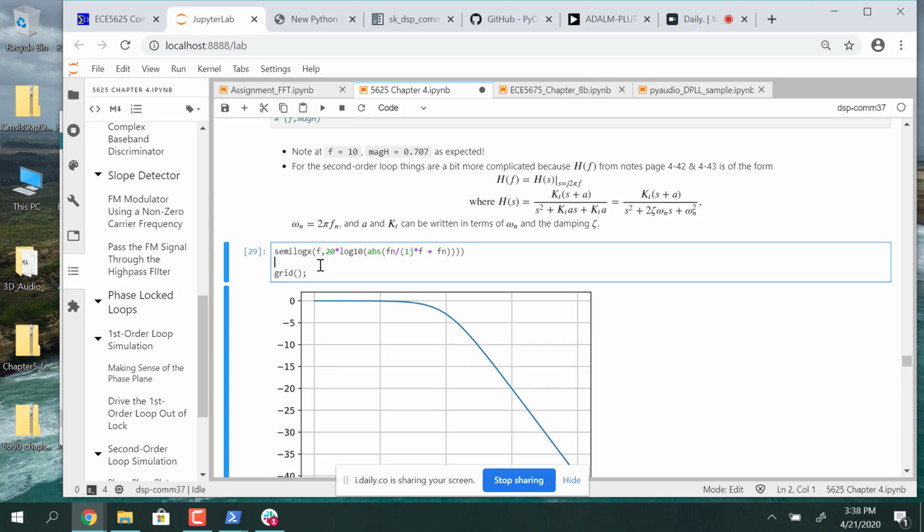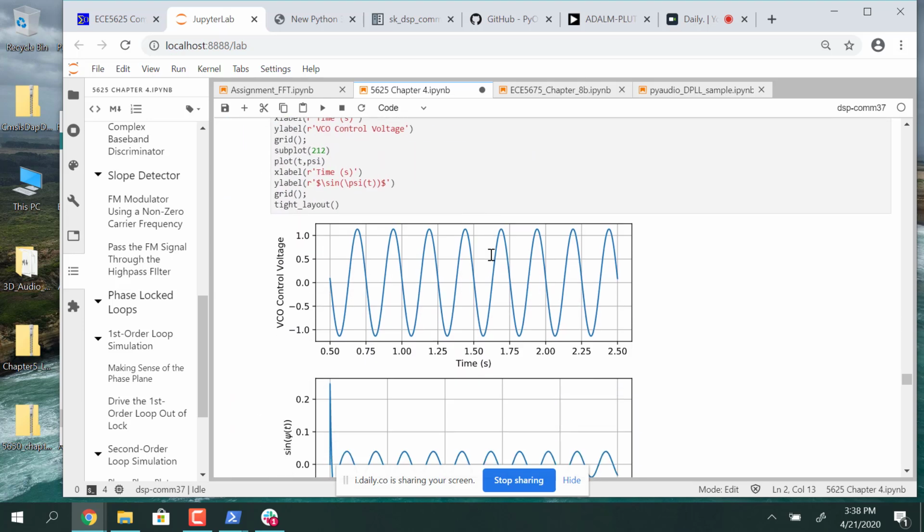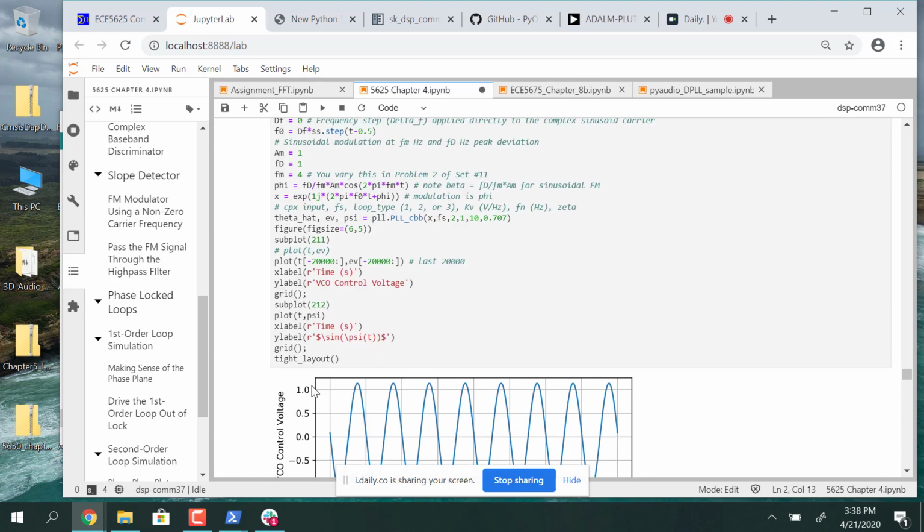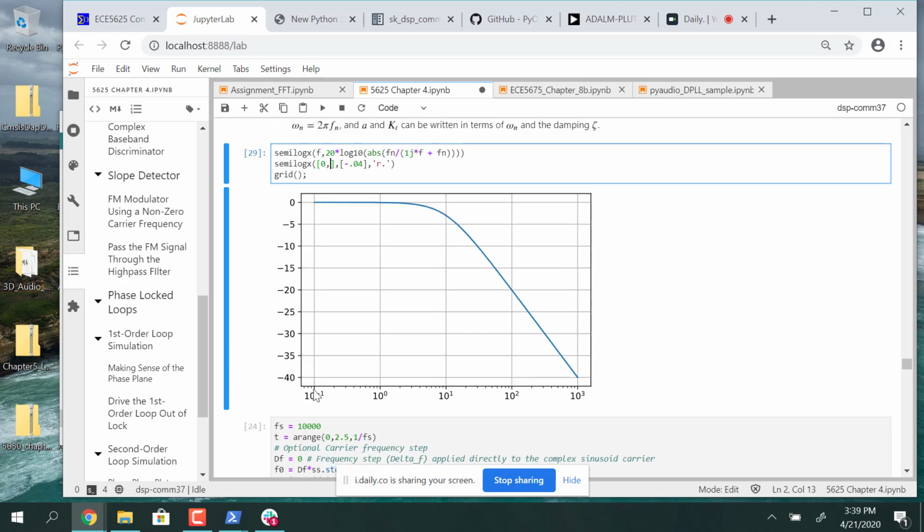So then what you'd want to do is just start putting in some of your experimental data. What I generally do is put them in as lists, and then I'll use red dots. So we already captured some data at 0 hertz. We were at -0.04, if you remember right. And then the second data point we collected, which was right down here, was 0.9289. So drop that guy in, 0.9289, and that was at 4 hertz.